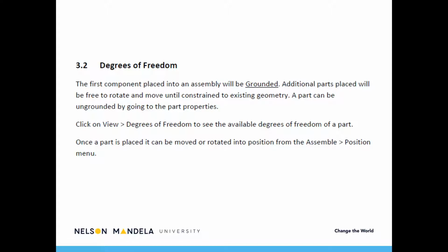If you remember, in the very first video I made, we made an example of a car. So we have doors and chassis and wheels and everything. Let's say the first component that you import when assembling a car will be a chassis, and then we will ground that one since it's a fixed component in the car. Everything else that moves, the wheels and everything, we will import last, and then we will use constraints with respect to the chassis. We will see when we do an example.